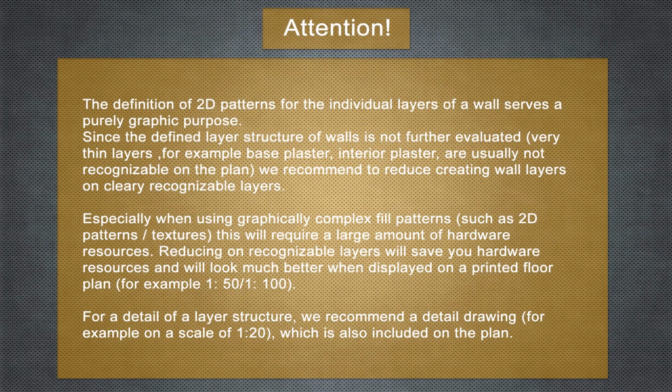Attention! The definition of 2D patterns for the individual layers of a wall serves a purely graphic purpose. Since the defined layer structure of walls is not further evaluated, very thin layers, for example base plaster or interior plasters, are usually not recognizable on the plan, so we recommend to reduce creating wall layers to clearly recognizable layers.